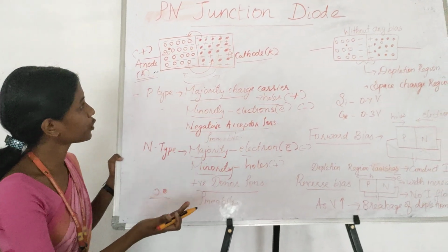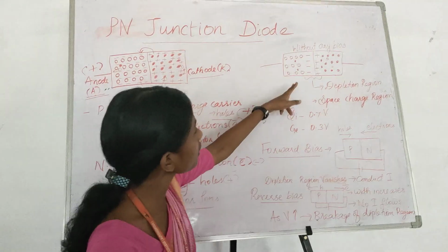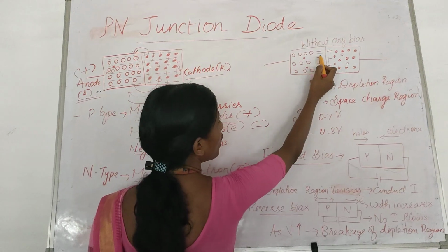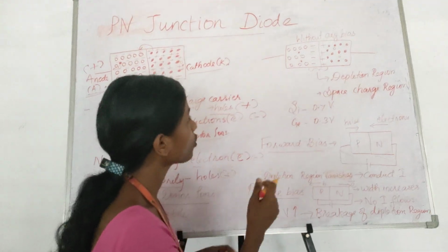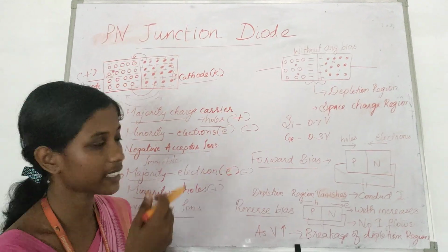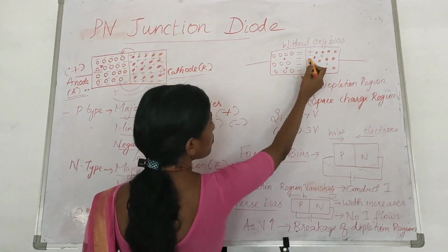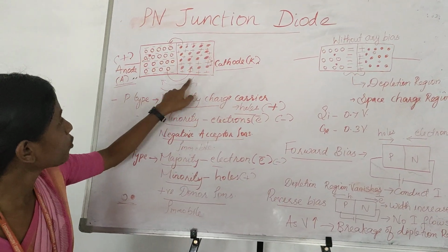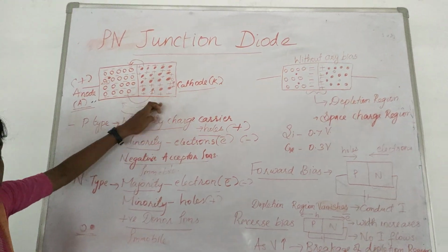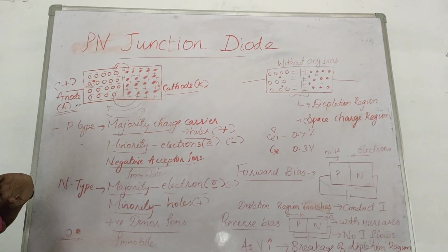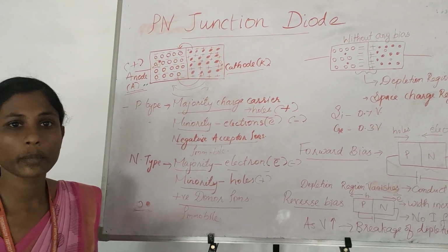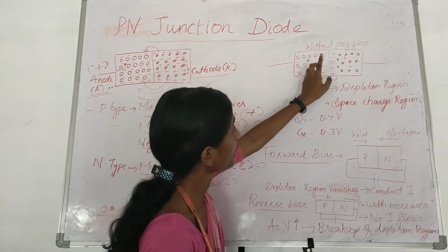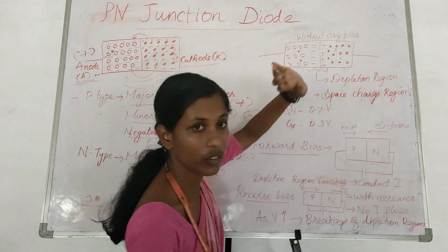The output of this recombination is that at the particular area of diffusion, or recombination, the remaining particles will be only immobile charge carriers. All the holes and electrons there get cancelled. At the junction, only immobile charge carriers remain. You may have a doubt whether the negative ions will move towards the N region and the positive ones towards the P region, but because they are immobile, they will not move, so this region will be filled only with negative acceptor ions and positive donor ions.